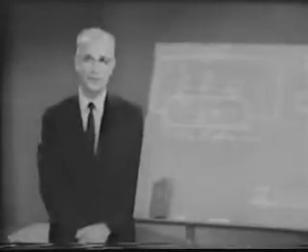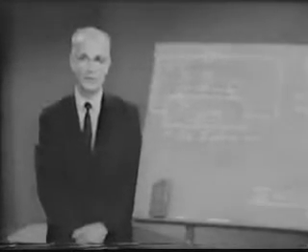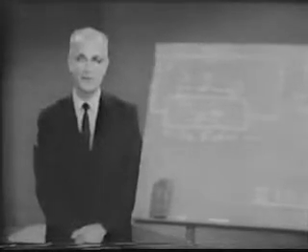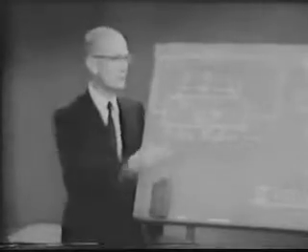These wires are pointed and make small area contacts to the surface of the bar. The detailed nature of the 4 electrical connections to the bar is important. In particular, the right-hand point contact is also used as the detector of minority holes.